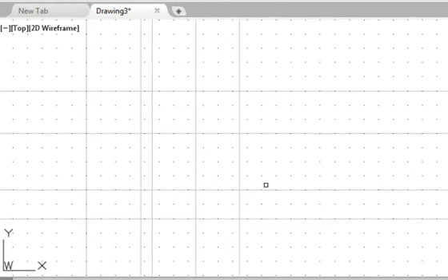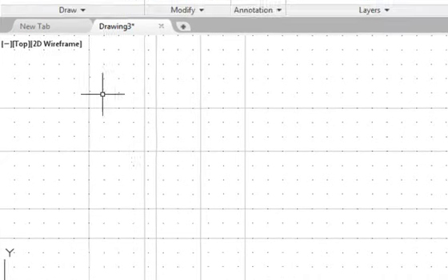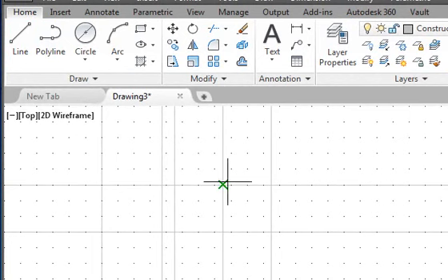We have roughly established regions for the 3 views. The side view region over here, the front view is next to it, and the top view in the top region. The upper right region is for setting up the miter line. Let us add the miter line. Activate the line command. Create the miter line by clicking on the 2 opposite corners in the region.